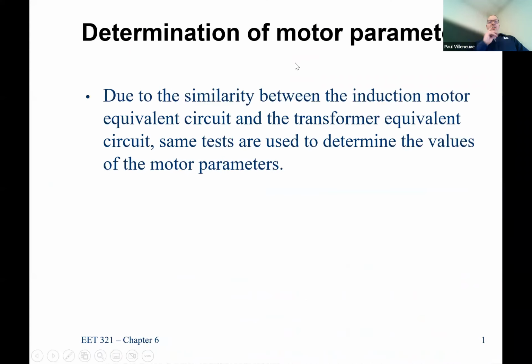All right, so let's determine some motor parameters. And remember, the induction motor is just like a transformer, but it's short circuited and it gets to rotate. So we're going to do very similar tests to the transformer, but the rotation has to be a slightly different approach. So the transformer test, we did the open and the short circuit test. What would be the equivalent of open and short circuit tests for a motor that rotates? Open circuit was another way to say the no load test. How do you have no load on a machine?